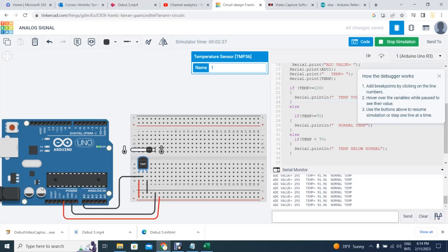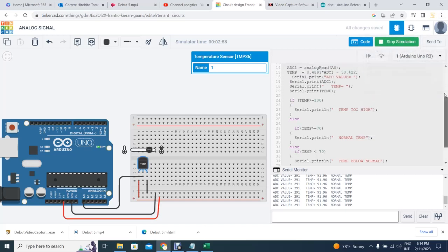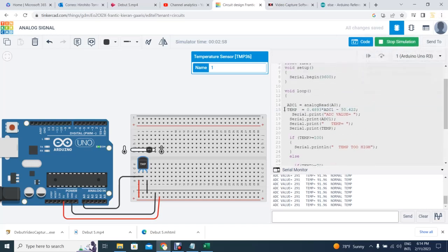But again, everything starts with this concept: a sensor that measures a physical property, in this case temperature. The sensor output is voltage. Nice, because then the Arduino doesn't need a voltage divider. That goes directly into, for example here, the analog signal A0. Then you read that signal, and eventually you do calibration, so you get the proper equation for that, which is this one. And it's interesting because this is linear. This covers a big range.